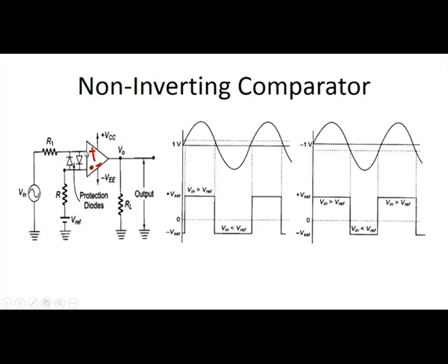Since we have to make these two input voltages equal, if you give a higher voltage to these input terminals, it will affect the operational amplifier. So, these two diodes keep the voltage across these two terminals at either positive 0.7 volt or negative 0.7 volt, that is the cut-in voltage of the diode, to protect the operational amplifier in any case.